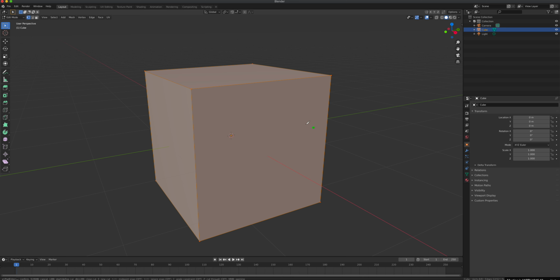What's interesting is I can make a cut anywhere actually, but that's not recommended. When you do that, there's no way for Blender to continue working from that particular cut. What you want to do when you use the knife tool is to land and snap into a particular line or point. You see how it snaps when I go like so? When I click on that line, I can then move my mouse and I get a cut. Not yet though. This is just a representation of where that cut will be.